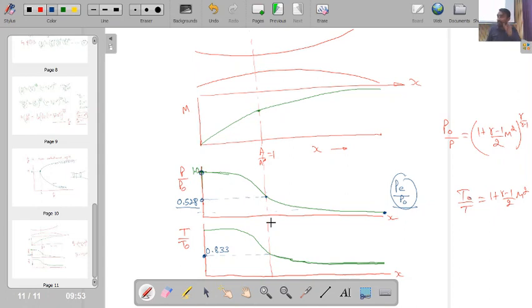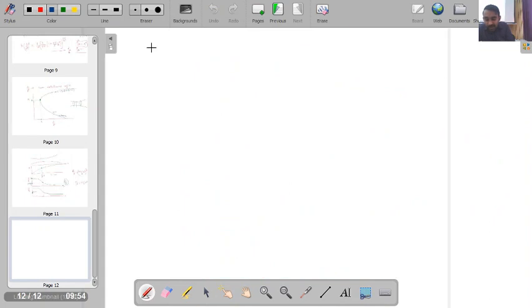Is this point clear? So pressure difference across the nozzle has to be controlled properly in order to make it work as an isentropic expander for changing the situation from subsonic to supersonic flow. Okay, if I deviate from this, then what will be happening? That is the question. If I deviate from this, it is for sure that I will not be able to achieve a Mach number of 1 at the throat. But what will happen? To understand this, let's now talk about the effect of pressure.